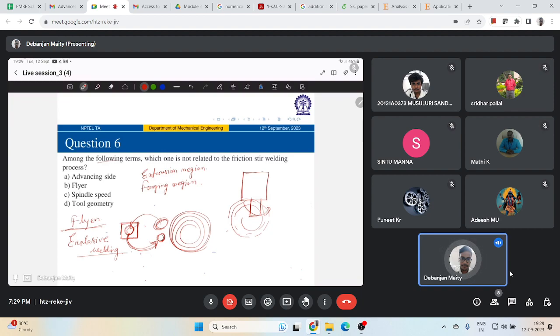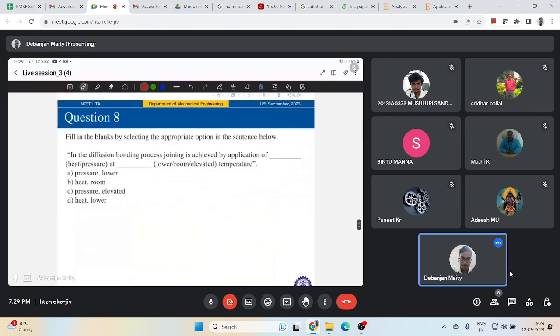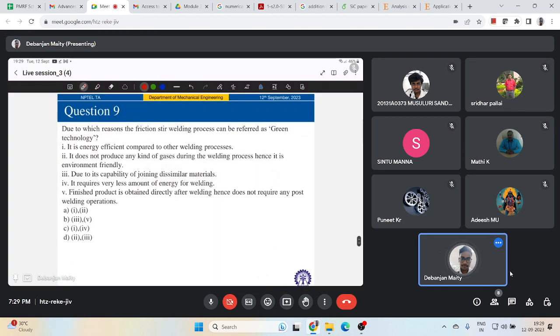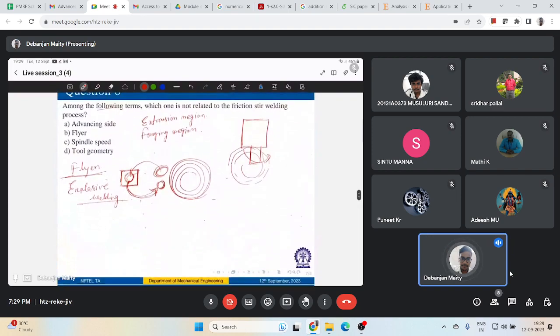Now, what are different process parameters in friction stir welding? These are some very quick question answer round kind of thing. Before that, I will just discuss the process parameters of friction stir welding. You have the tool RPM, right? You can have clockwise or counterclockwise direction. Because of that tool rotation, as I was saying, there is stirring and mixing of the material around the pin, right?